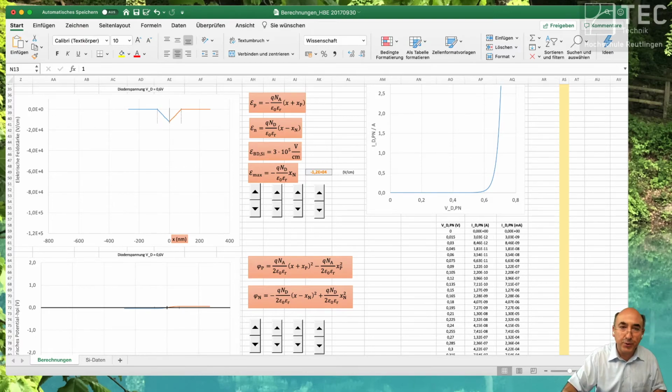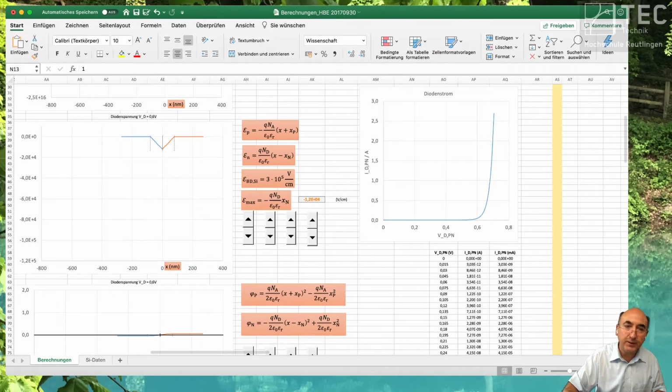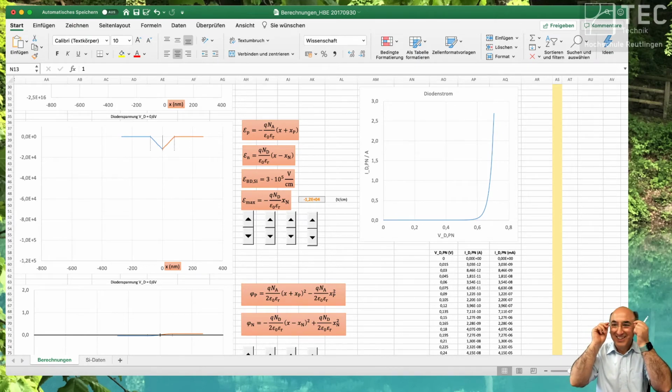So this is the theoretical level of the current of a diode you are producing on 1 square centimeter with a doping level of 10 to the power of 16. That's it. And the rest are parasitics. Okay, so you have to start designing these devices at some point, and this is the starting point of your design.